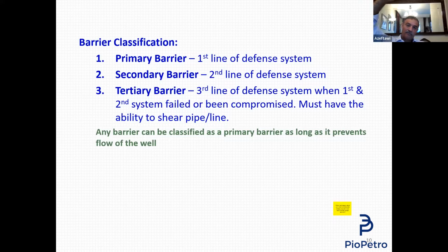And then we went through the length of the well. The well is full of mud. The mud density is 9 ppg, 9 pounds per gallon. We run all the way. When we reach 13,000 feet, the supervisor or the operator on the top pushes the button. So the explosive charge fires. Now the guns hit the casing, make these holes, and hit the formation, making the perforation tunnels.